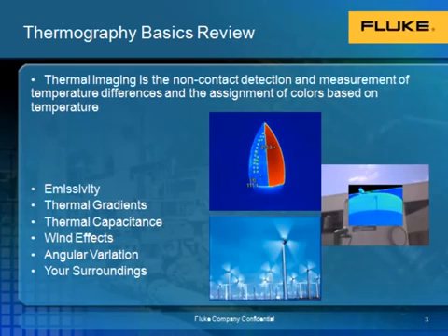As you see in the picture of the iron, half of it is much warmer than the other. What's happening here is half the iron is coated in a black paint. This makes it a much more thermally friendly surface. Shiny surfaces like the left side of the iron are not very thermally friendly and lead to false readings.